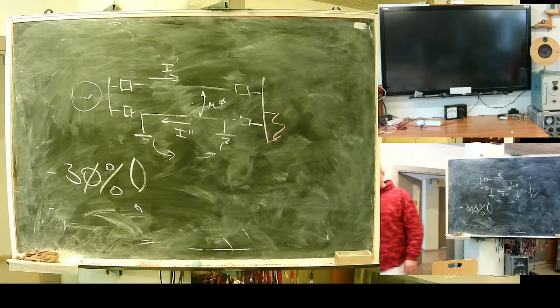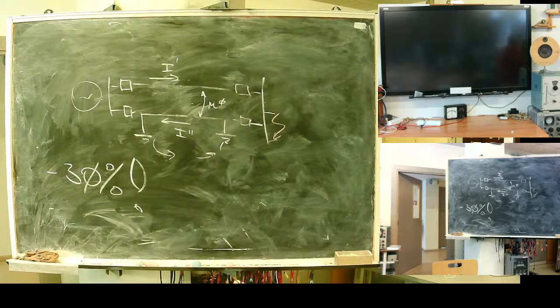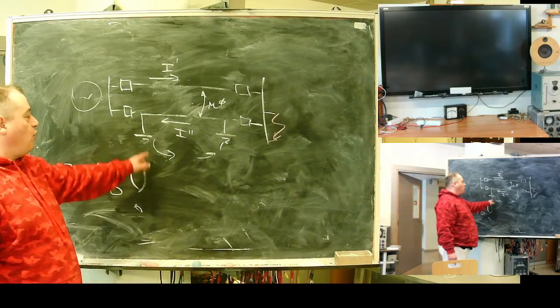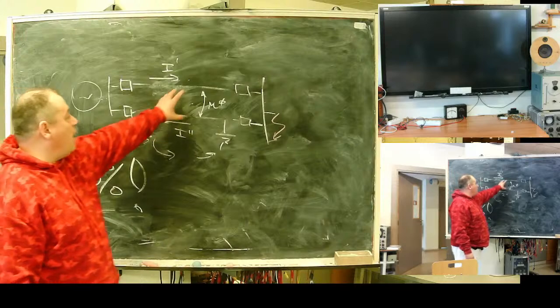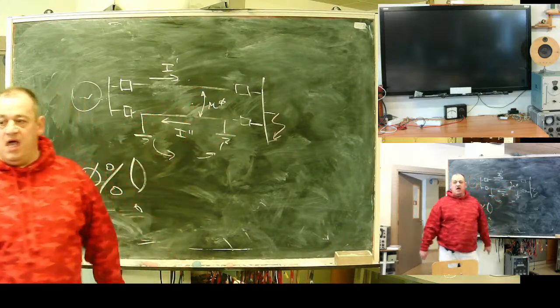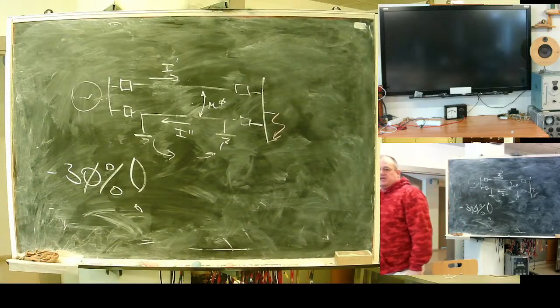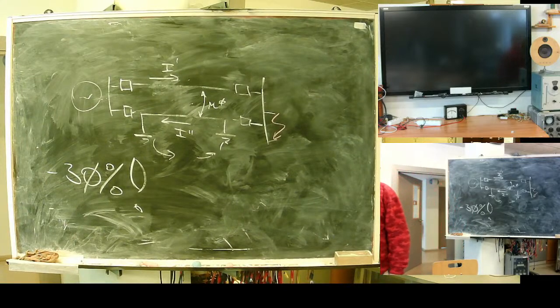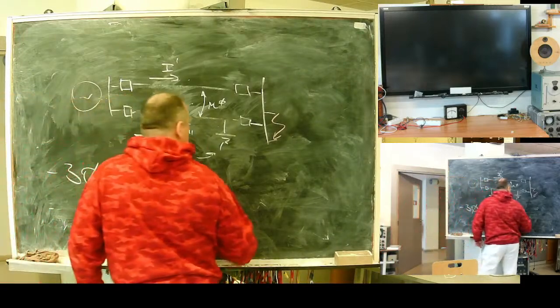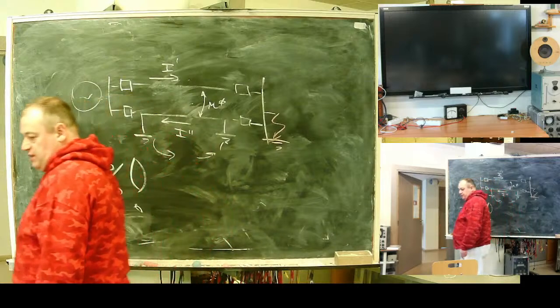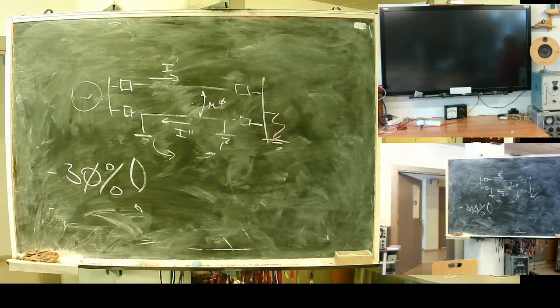For repair conditions, settings of distance protection must be recalculated and changed. It is serious. When parallel line is switched off and grounded, coupling between them still remains. In normal regime, this coupling isn't very serious. While linemen sometimes say, hey, come on, there's current here, we see current. It's induced. But in case of earth faults, this coupling will be serious.